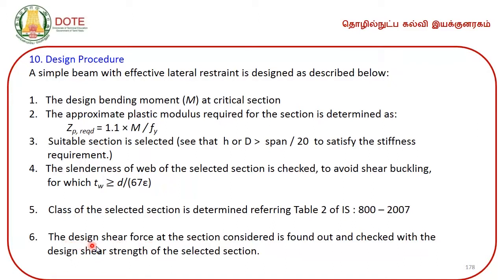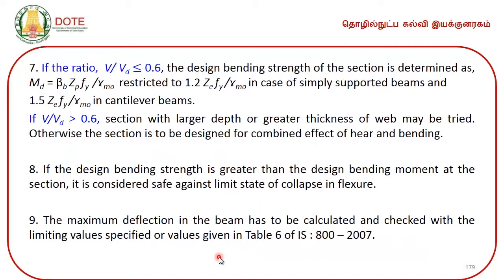If this design shear force is less than 0.6 times the design shear strength of the selected section, the section selected is OK.